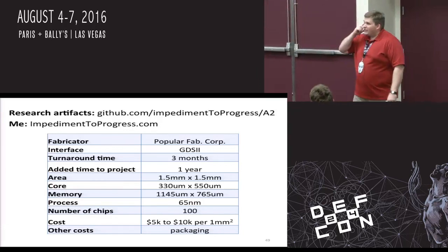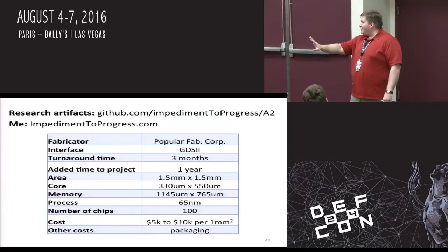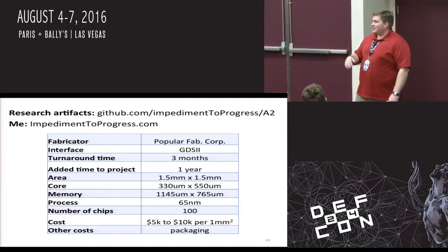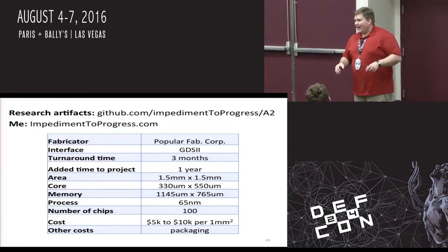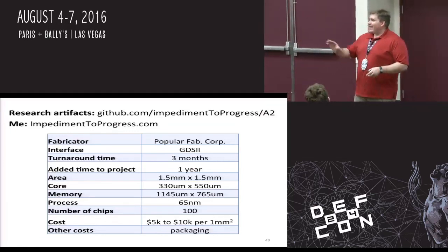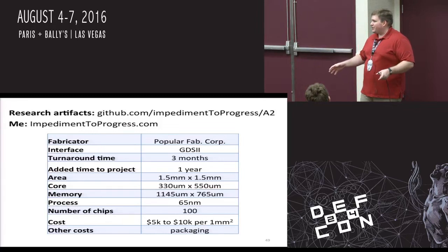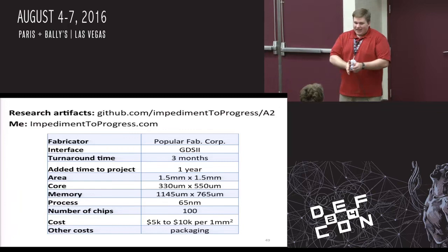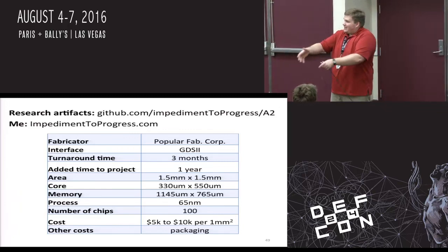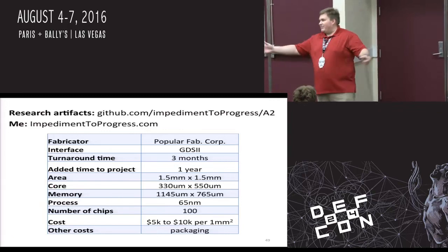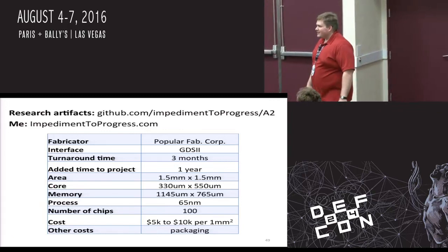And in terms of how you design it and even how you fabricate it, there are coming technologies in split manufacturing, 2.5D, and 3D integration. And I think those can all be combined. Then when you divide and you say, I only need to trust 1/100th of my design, that makes it more amenable to formal and functional verification, and you can actually spend more time on that. I think you really should say, here's stuff I don't care about, I don't need security, and here's stuff I do need security in. Let me focus my efforts on the stuff where I do need security. Right now it's just one big gobbledygook.